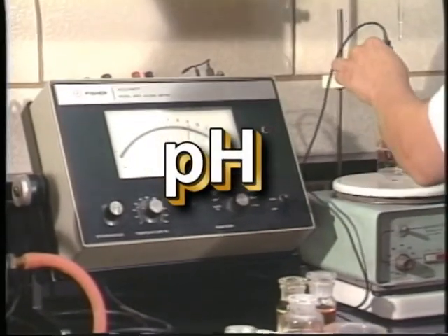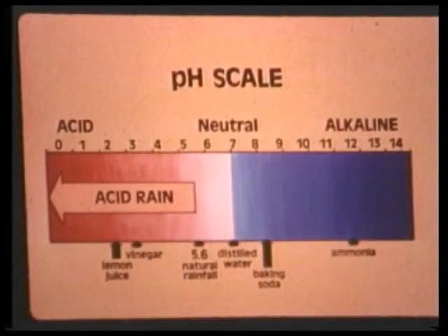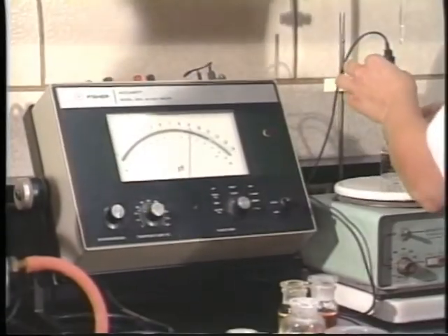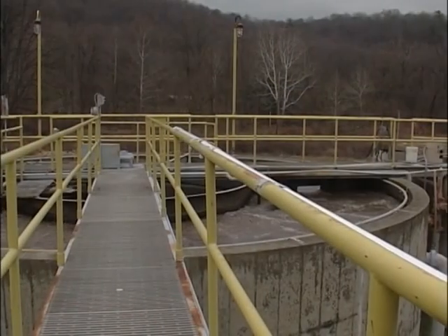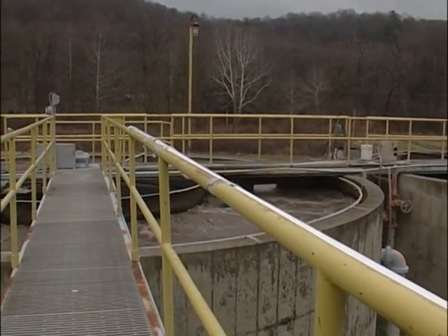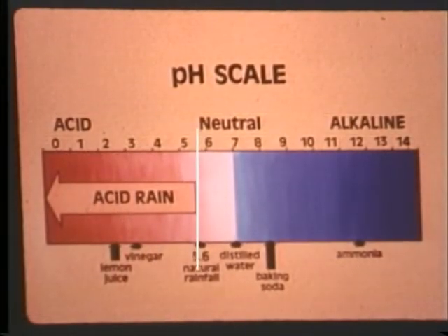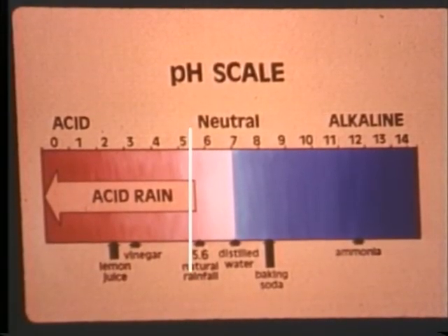Factor number 6, pH. The broad range for nitrification is from 6.5 to 8.0. However, nitrification typically works best when the pH is above 7.0. pH readings outside the recommended range could lead to an inhibition of the nitrification process. A sudden and drastic drop in pH could indicate that all the alkalinity has been used up.